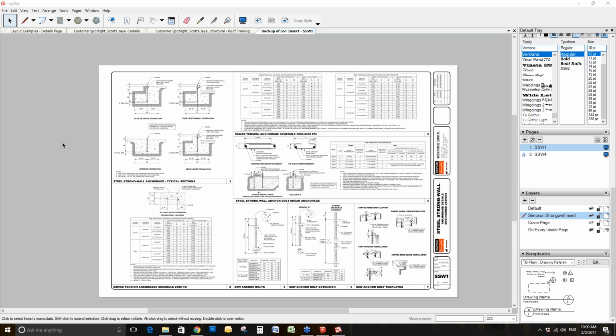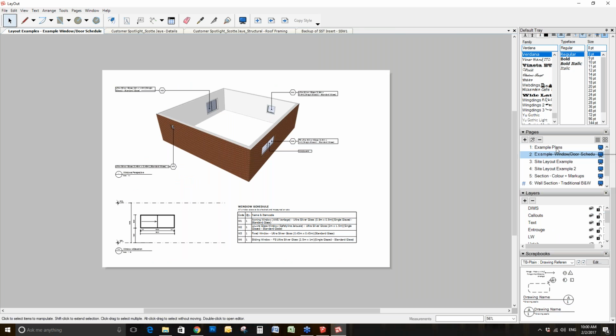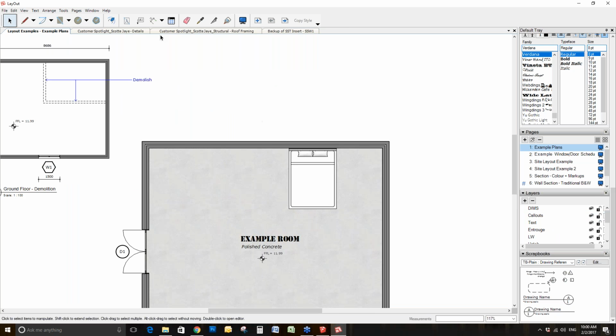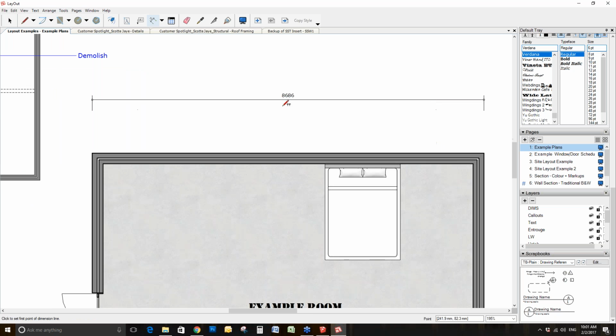All right, so another question is, is there a quick way to adjust dimensions and change the length of the extending line? So it's a funny one, because in Australia, we typically do keep very short dimension lines. So if I come into here and draw a dimension, you can see it's going to pick it up. Let me just do it like so.